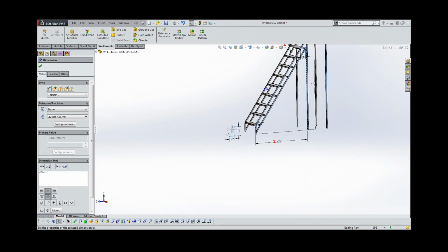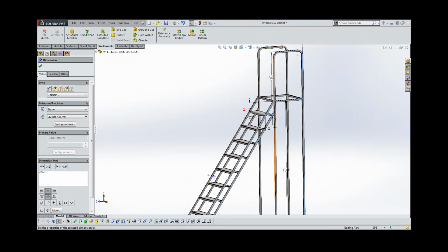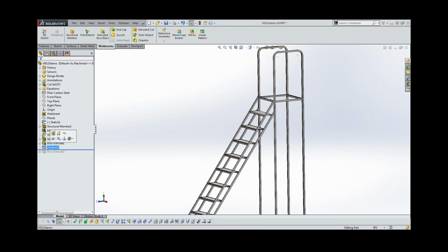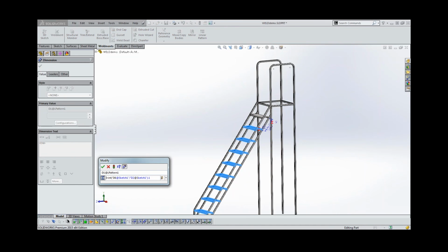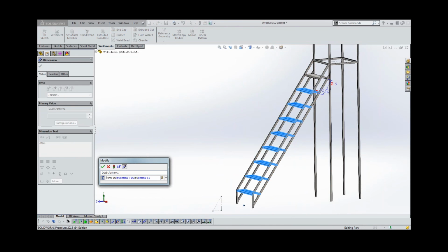And the same thing for your instance count. Let's go ahead. We'll double click the sketch again. We'll bring up the instance count. And here we're actually using an integer function and linking it to our height and the depth of the steps, to generate this pattern.